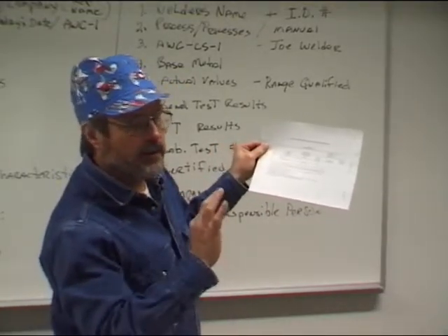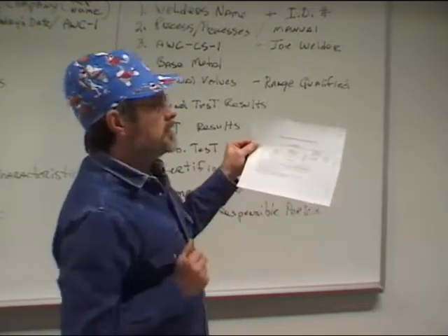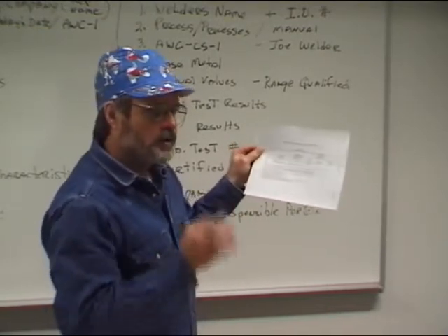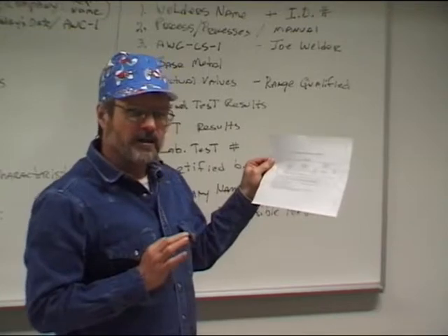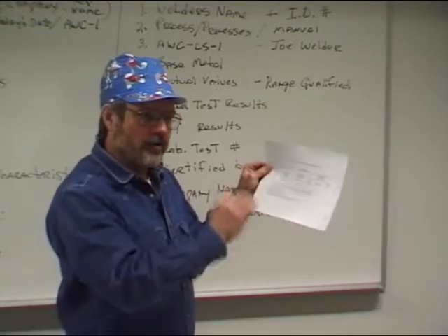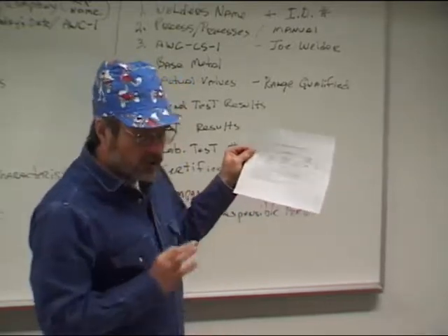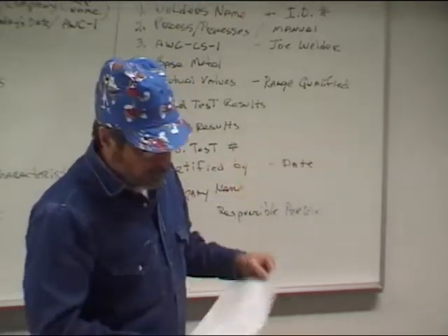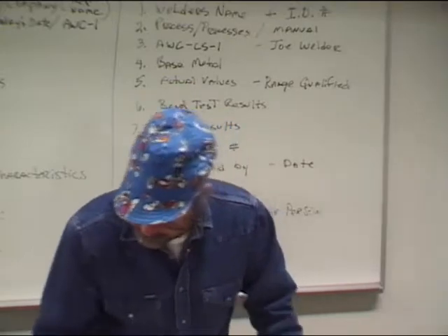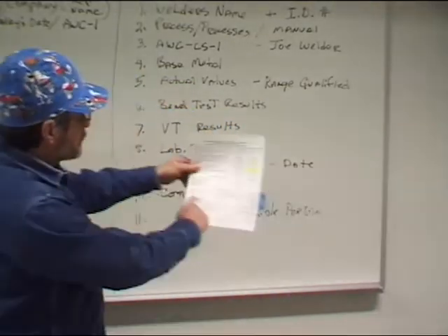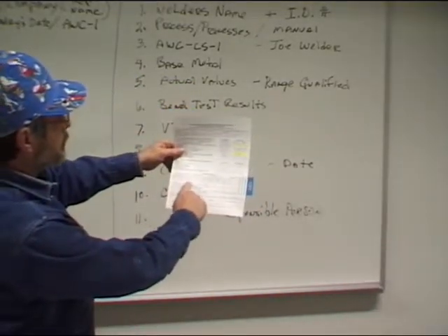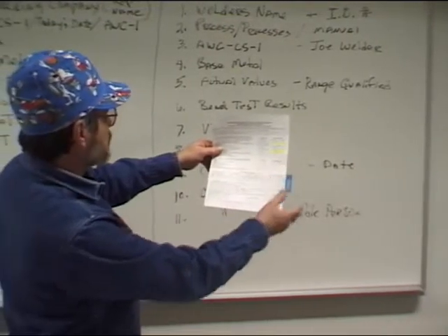So always read the notes, because on the face of it, you might think it's telling you one thing, but when you really look at it, kind of like trying to read the IRS code, you know, it'll say, go back to this paragraph, then flip to that table and do this other thing. It can get pretty complicated, so make sure you read your notes. So we would do 2 face and 2 root bends. So you've got that paper in there. And so that information then would be entered here. Face bend, root bend, satisfactory, satisfactory.